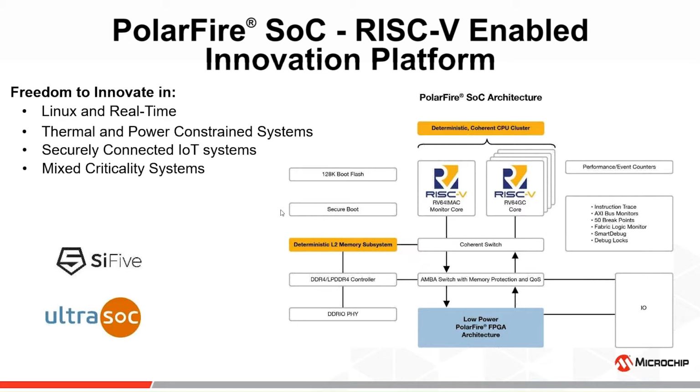We also have an integrated DDR4, LPDDR4 controller and PHY, and a slew of hardened peripheral IPs that connect to the processor subsystem and the FPGA fabric. This is a true innovation platform wherein you can get deterministic real-time execution alongside a rich operating system like Linux. Thereby, it provides the simplicity of using a Linux-capable system while also doing real-time system control. It is built over our existing strengths in designing really low-power FPGAs and SoCs, so it would be ideal for thermal and power-constrained applications.